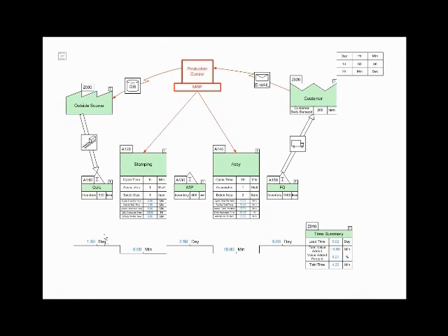So just to do a quick check, as we expected, 1.5 days of non-value-added time here, 6 minutes of machining time here. If I look at the value-added percentage, this would be value-added over non-value-added, it's less than 1%. It's only 0.2%. And really, this is not atypical. It really represents a huge opportunity. And if you look at the time it took for that scissor just to go through the manufacturing flow, and we really haven't considered the information flow yet, you can see that it took 9 days.